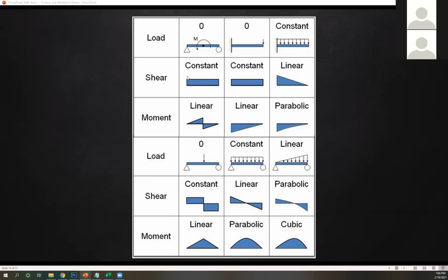And then, starting from the left, since your area is above your equilibrium line, you have a positive slope, right? So positive slope upward. Then you have a counterclockwise moment. So counterclockwise is negative, so you're gonna go down. And then on this portion, your area is still above your reference line. So you're still gonna go upward slope.